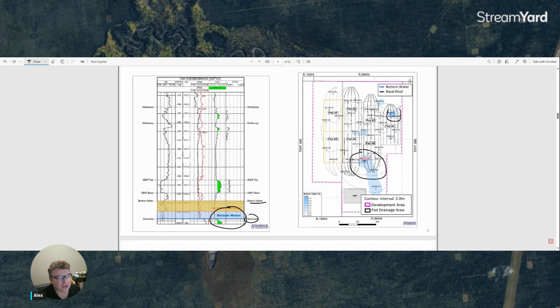And obviously, we have pockets here and here of water, so the operating team needs to keep a good look on the bottom hole pressure, BHP, so it's maintained in such a way that the water doesn't have an incentive to flow into the production well. Here below we can see the different heights of the bottom water, based on the color specified.